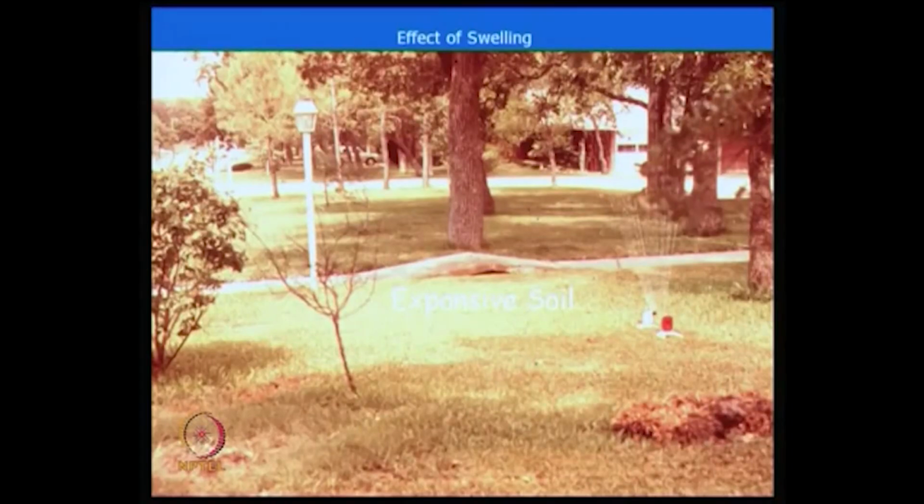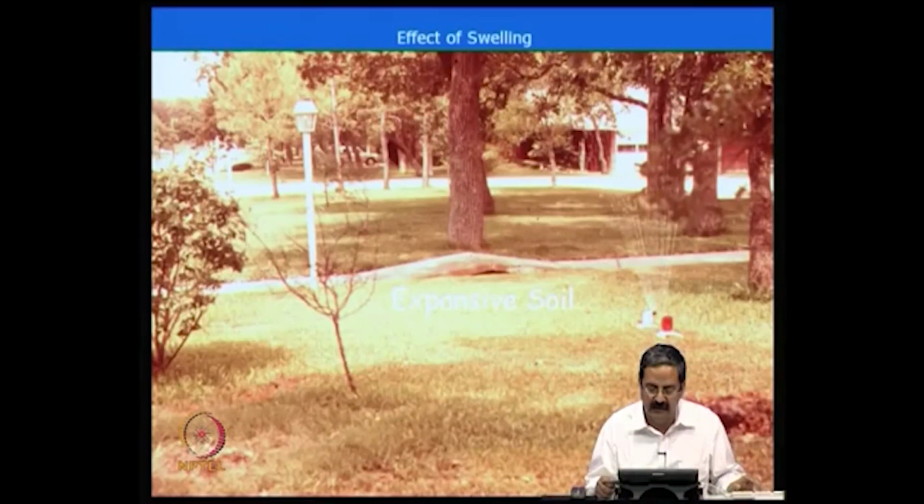What I would like to show here is that in the case of an expansive soil, the particular area, as I just mentioned a few minutes back, the expansive soil, which in India is called black cotton soil, its expansive nature is because of the presence of montmorillonite in its clay structure. So, when water is added to the system, like during the rainfall, there is a tendency for the soil to heave. The soil structure imbibes a lot of water, and then the pavements on this could heave.